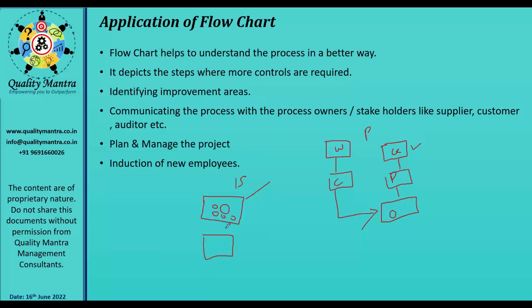Now you know that you have to put the tray after 15 minutes. It means you must be having the trays stacked nearer to this machine. Otherwise, what will happen, after this finishes you remove the tray, you walk to the other area, you collect the tray and then you put it. The downtime will be there, maybe 2 minutes, maybe 3 minutes. But if the trays are here, there will be no downtime. You will just remove, you will just put it, you will start the machine and then you will put the output to the designated area, so that you can improve your productivity.